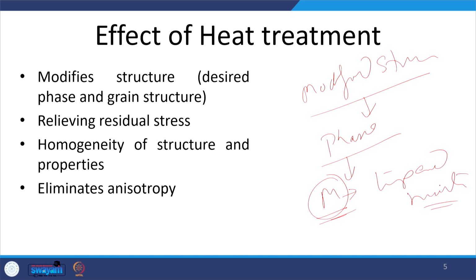Okay. This is one. Similarly, the grain structure can be modified, and the phase structure also, for example, if there is a solid solution, then through heat treatment we can have suitable precipitates in order to impart the desired strength. In metals which are primarily strengthened through grain refinement, the heat affected zone experiences significant grain coarsening. Okay, a very coarse grain structure.